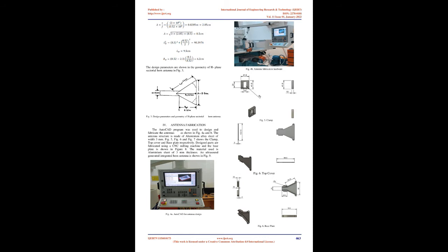Fig. 1. Different configurations of electromagnetic horn antennas. The H-plane sectoral horn is one whose opening is flared in the direction of the H field while keeping the other constant, and is shown in Fig. 1b. The horn is fed from a rectangular waveguide of interior dimensions A and B, with A the broad wall dimension. The aperture is of width A in the H-plane. The H-plane cross-section in Fig. 2 reveals the geometrical parameters. Fig. 2. Geometric parameters of H-plane sectoral horn.